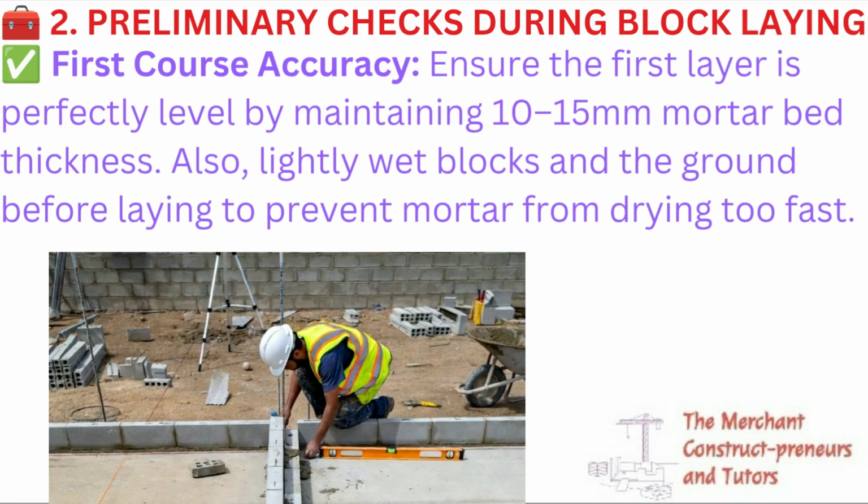Now I used to hear most masons tell you this first block doesn't matter jare, plaster will cover it up. No, do not accept that as a construction supervisor. You ensure that the first layer is perfectly level and vertical. Also the mortar that is used, you ensure that it is of the same thickness.